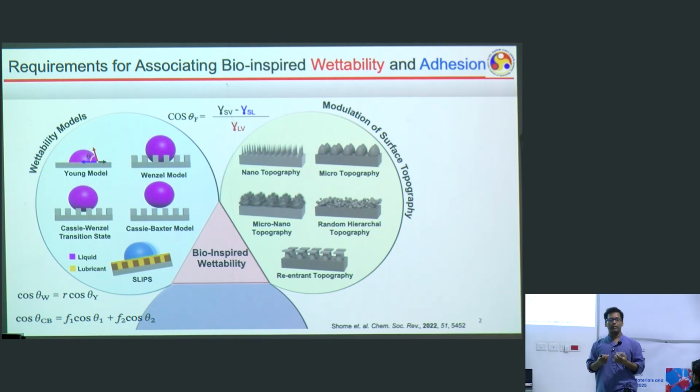Non-adhesive superhydrophobicity means that if you tilt slightly less than 10 degrees, I'll talk about that in a little more detail, the beaded water droplet can easily, elegantly slide or roll off. During that process, it collects all the dirt and dust and leaves behind a clean and dry interface.